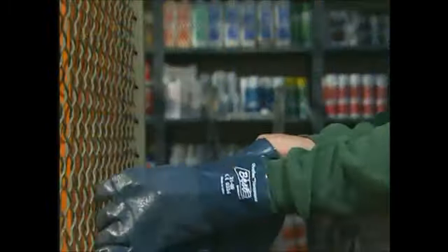Examine your gloves for signs of wear or failure every time you put them on. Gloves can fail due to permeation, or a chemical seeping through glove material, or penetration, when a glove is torn or punctured. Look carefully at the tips of the fingers and between fingers for cracks, pinholes, or excessive wear. If there are any signs of damage, replace them.